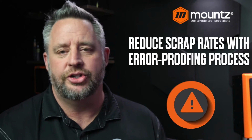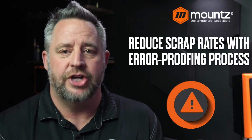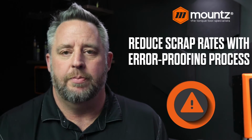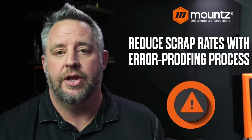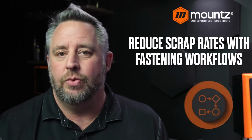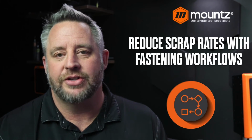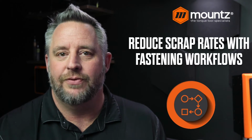So when the torque is achieved, we also have a secondary or error proofing check against the amount of turn that happens with the system, as well as looking at the actual torque and whether it is within the parameters of percentage that we have requested. And there are other items within the error proofing process that we can use, but we'll leave that for another webinar.